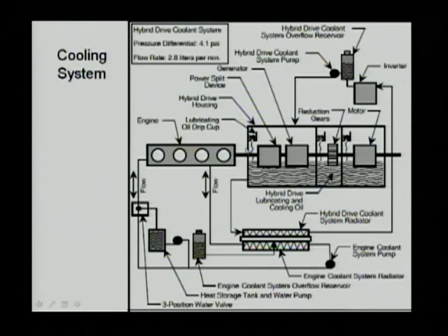So this system is usually cooled at a lower temperature. A typical coolant temperature is about 70 to 80 degrees C in the power electronics and motor cooling loop. But it's usually around 100, maybe 110 degrees C, or even 120 degrees C on the engine side. It depends, of course, on the season and the operating condition. That gives you a rough idea of how those electrical motors and power electronics are cooled, and how it is designed in a Prius, a system similar to a Prius hybrid.